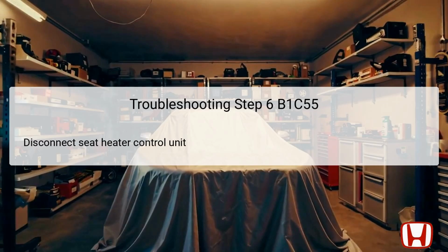In the sixth troubleshooting step for the DTC B1C55, you will need to disconnect the seat heater control unit, specifically the 14P connector. The seat heater control unit is central to the Odyssey's seat heating functionality, managing signals dispatched to the heater based on the thermistor's readings. Disconnecting this connector allows for safe and thorough resistance measurements at the specific terminals.